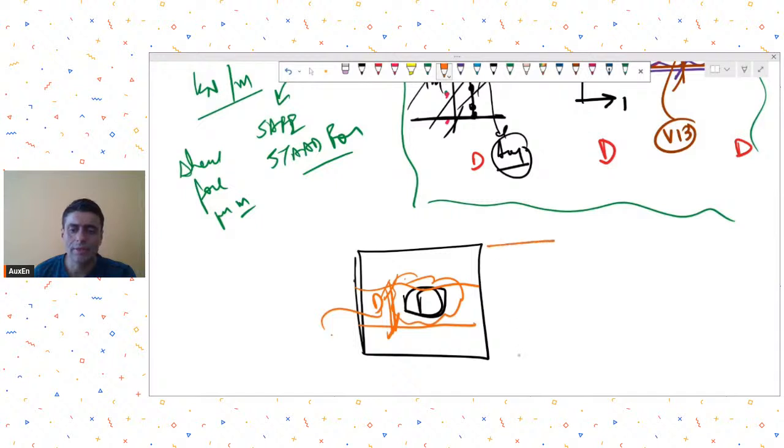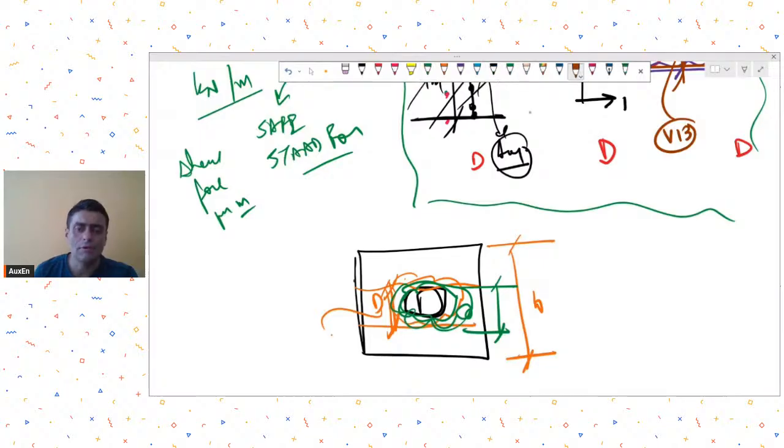So although we take this width, if you see the shear stress concentration, it is more in this region, which is somewhat equal to this dimension of the column, especially when I am checking for, let's say, V13 shear. So V13 shear will be concentrated in this region. Now some people say that we should take this column dimension width when I am checking V13.